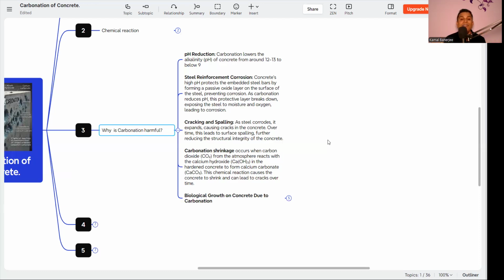Now it is open to moisture and chloride, and then the corrosion starts. That is why carbonation of concrete is very much harmful. Corrosion of the steel due to carbon dioxide is called carbonation-induced corrosion. In the urban areas, there are a lot of cars every time, and the carbon emission from the cars can cause carbonation-induced reinforcement corrosion in bridges and so on.